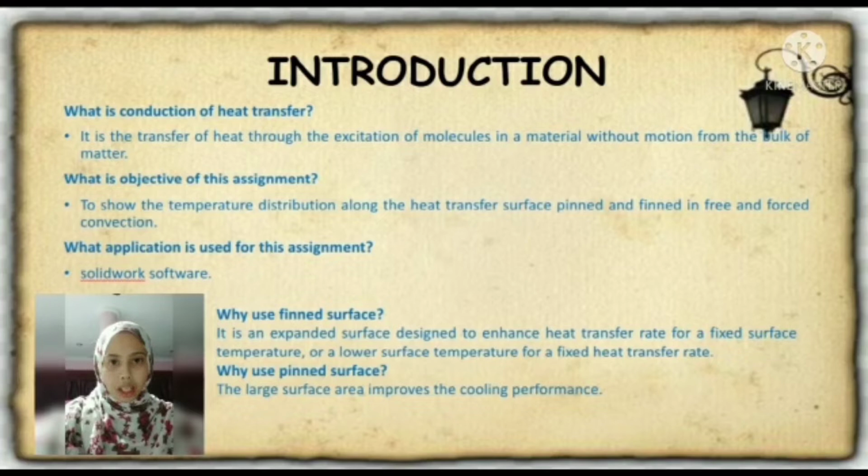In this assignment, we have used SolidWorks software and made sketches and analysis of the fin surface and pin surface. The reason we use the fin surface is because it is an expanded surface designed to enhance heat transfer rate for a fixed surface temperature, or a lower surface temperature for a fixed heat transfer rate. Meanwhile, we use the pin surface because the large surface area improves the cooling performance.